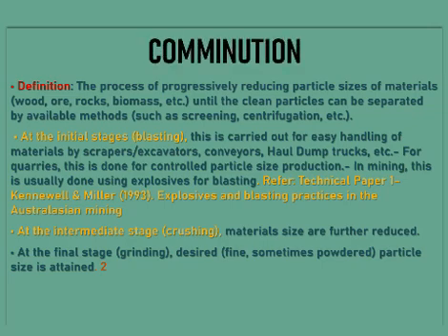Comminution. Definition: the process of progressively reducing particle sizes of materials, wood, ore, rocks, biomass, etc., until the clean particles can be separated by available methods such as screening, centrifugation, etc. At the initial stages, blasting is carried out for easy handling of materials by scrapers or excavators, conveyors, haul dump trucks, etc. For quarries, this is done for controlled particle size production.